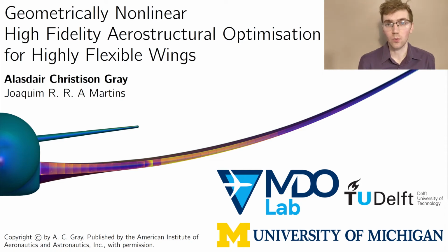In this work, we demonstrate how we extended the high-fidelity aerostructural optimization framework MACH to include geometrically nonlinear finite element formulations. We also demonstrate how geometrically nonlinear phenomena affect the optimal structural sizing of high aspect ratio wings.